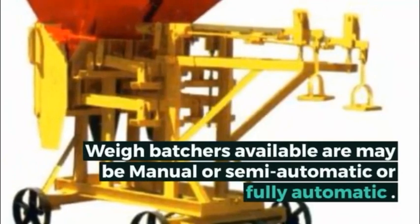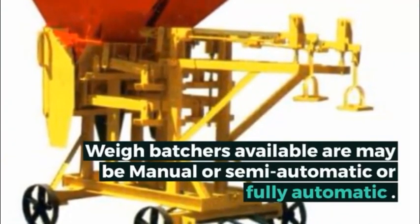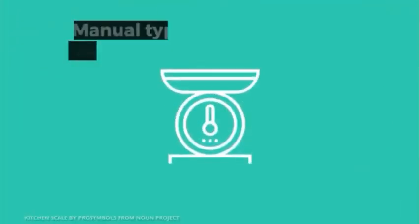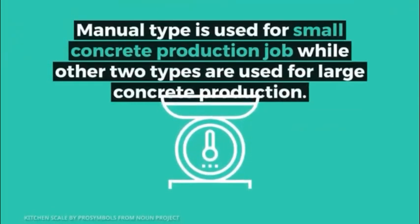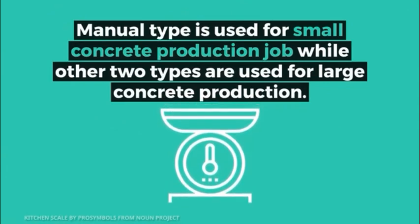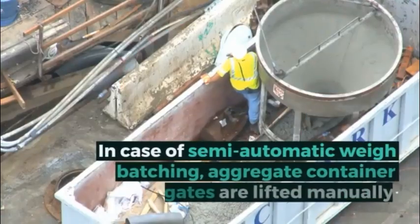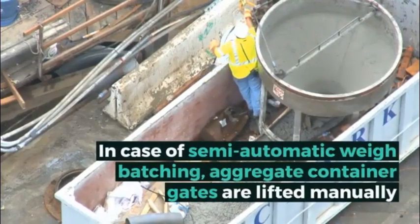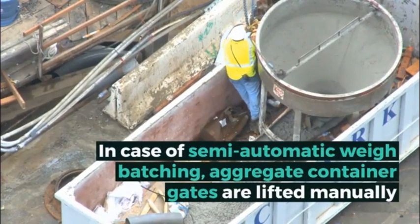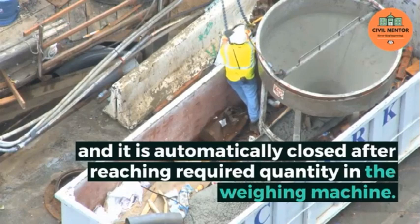Weigh batchers available may be manual, semi-automatic, or fully automatic. Manual type is used for small concrete production jobs, while the other two types are used for large concrete production. In semi-automatic weigh batching, aggregate container gates are lifted manually, and are automatically closed after reaching the required quantity in the weighing machine.